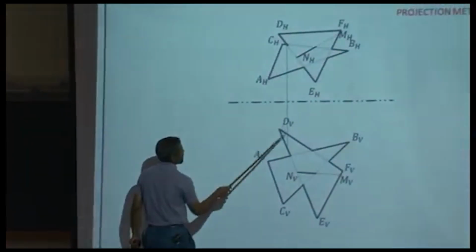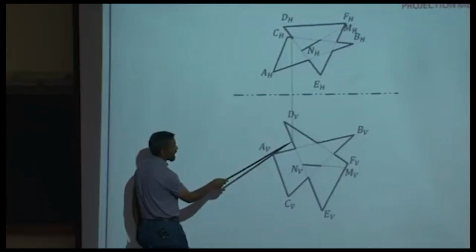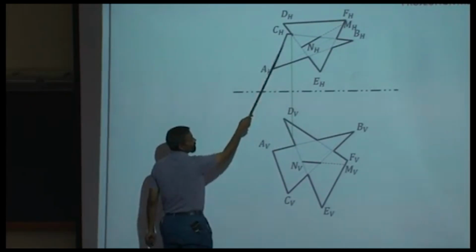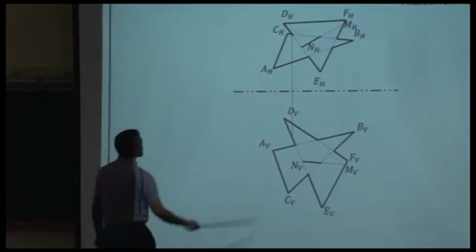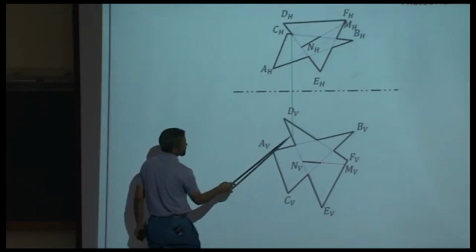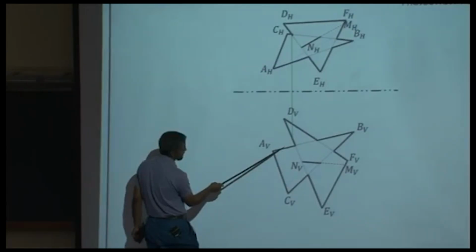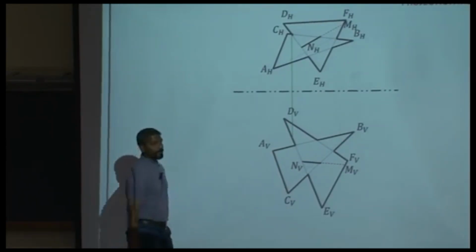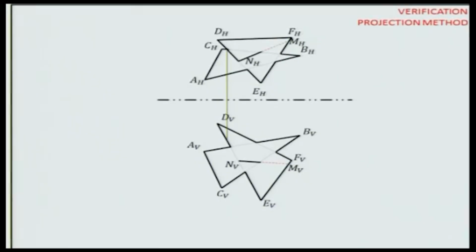If you drop a vertical from here, okay, whichever edge is up in height in the front view will be visible in the top view. Logic is precisely the same. So if you drop a vertical from here, okay, DE seems to be getting hit before BC, right? So it is this portion of DE that would be visible and therefore solid. Agreed? Okay.